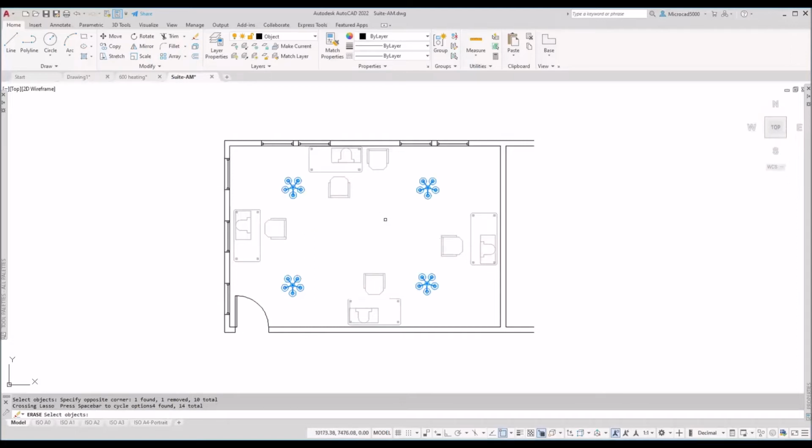Okay. You can also go into, if you like, a permanent remove mode. So R to remove. Now the command line says erase remove objects. I'll remove that chair there. I'll remove this setup down here. So I'm in remove mode. If I go back in letter A to add, I'm back into add them into the selection set. Add those two in there, add that one, and so on. So you can add, remove until you're happy, hit the enter key, and it strips them out. Okay, so that's the adding and removing objects.